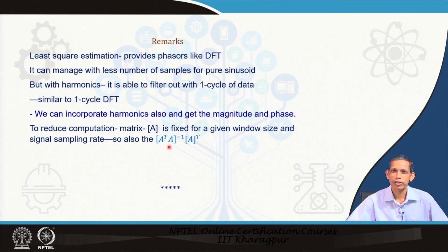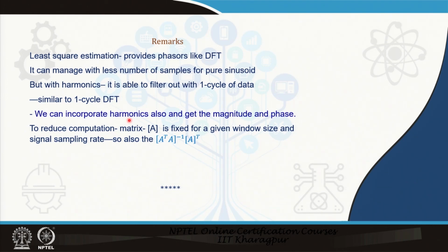Therefore, there is no need to always compute the inverse matrix, and that reduces the computation burden in the process. So, overall, least square is another attractive technique for Phasor estimation. We will consider in the subsequent lecture how this technique can be useful in different other applications also.